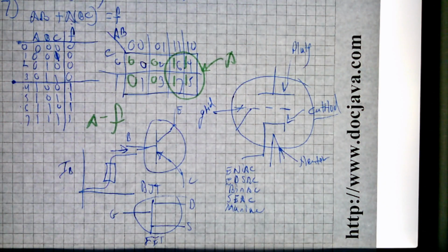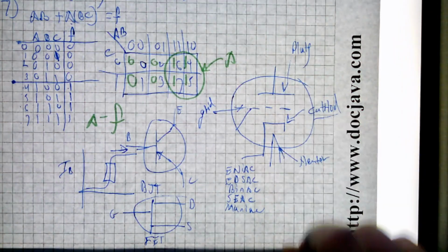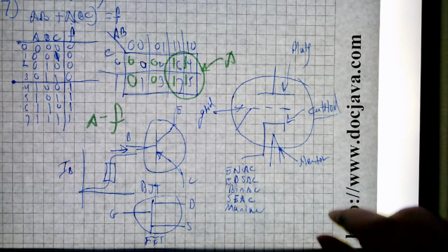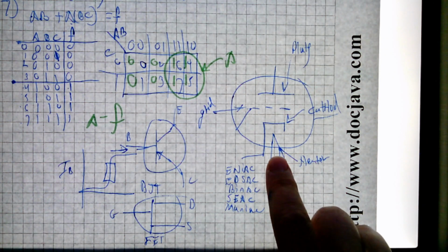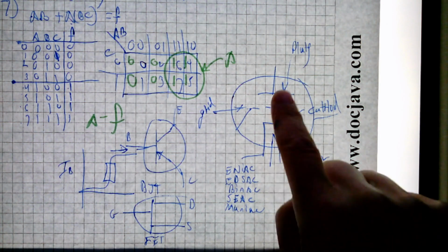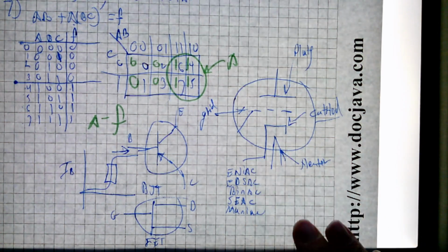So then there's another thing that says triodes can't do high power. That's not true. They can do in fact, the voltages here will kill you. These are 500 volts, 800 volts across the cathode and the plate. Very high voltages. The filament is relatively low voltage. That's around 6 volts AC. But the biases, the grid voltages, these are big time voltages, usually.